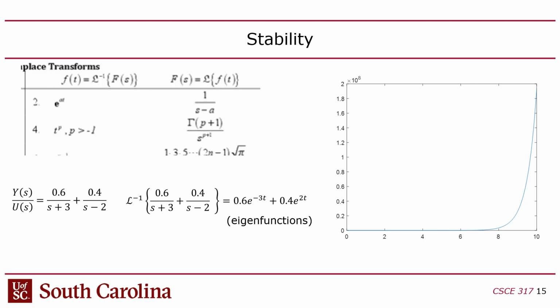How do you figure this out? Well, it's the transfer function. Remember I said that the S domain of an impulse is 1. And I also said that you multiply two transfer functions, because the transfer function of an impulse response has no input. It's just 1, right? So basically, what you end up with when you do this is the impulse response, essentially. If you plot this relative to time, it's the same thing you'd get if I hit the transfer function with an impulse, right?